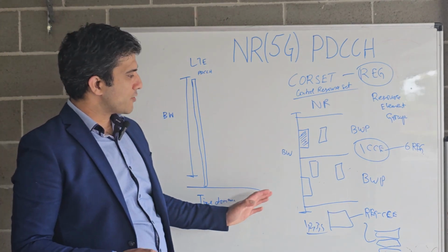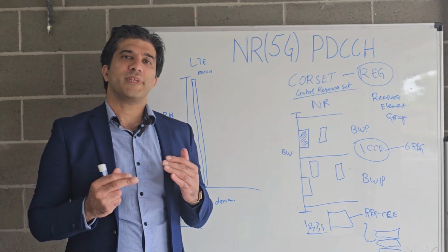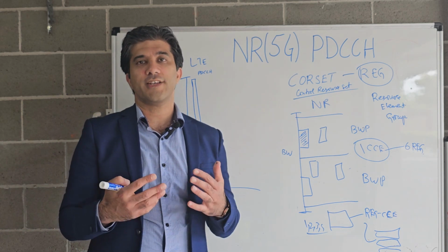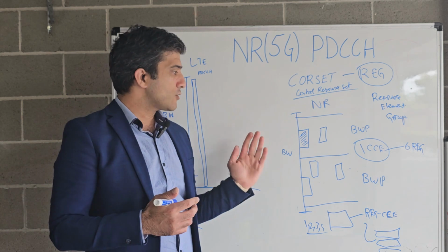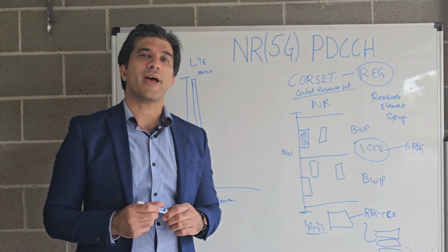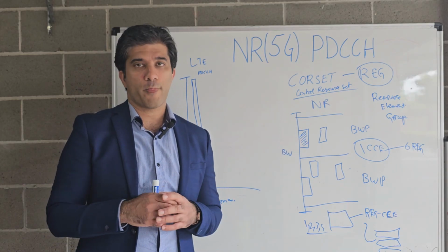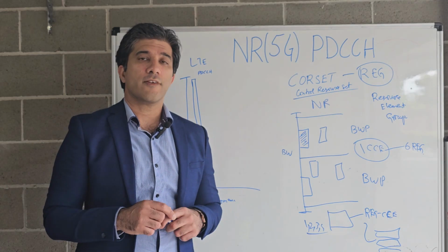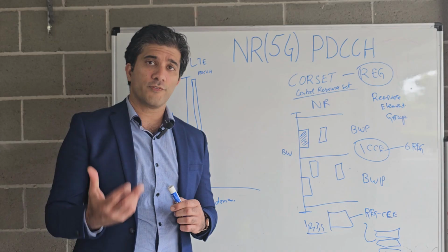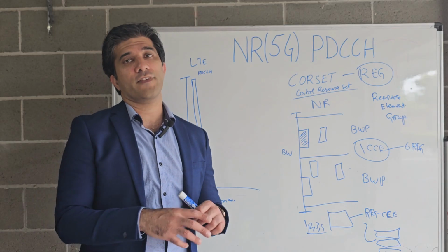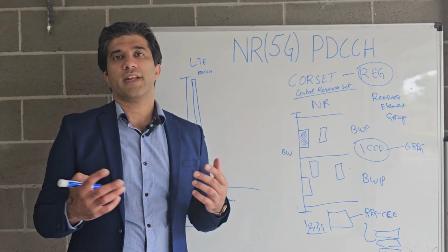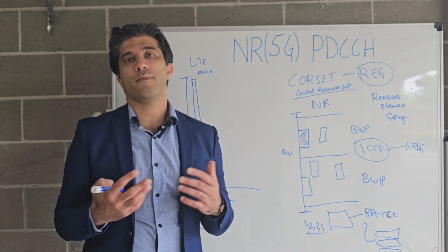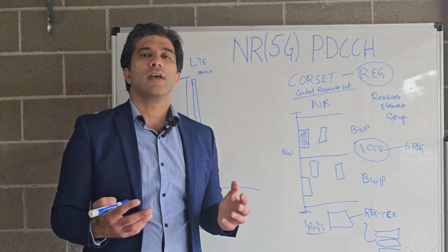Based on this concept, your PDCCH search spaces, or where your phone or UE tries to listen for a PDCCH, are not spread across the bandwidth. What's the advantage? For example, take an area where we have a lot of PDCCH usage and a lot of control signaling. That could be an area with a lot of handovers or short calls. That could be an area where we're having a concert, a cricket match, or anything where a lot